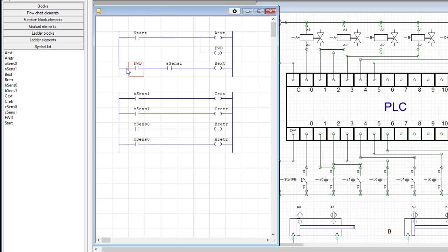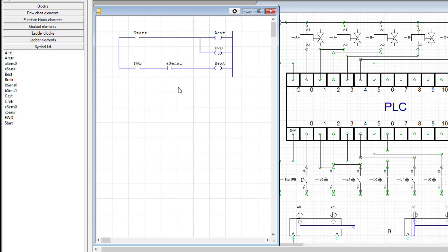All right, the next rung is going to look very similar. It's going to have two inputs and an output. I'm just going to get rid of this down here. It really is not helping us at this point. I'm going to make a copy of this rung. So the quickest way, Control C, Control V, and then click.